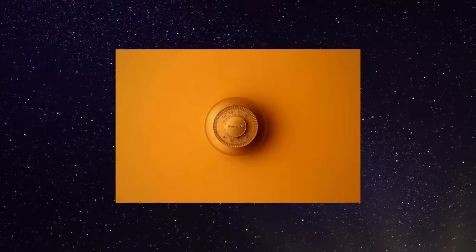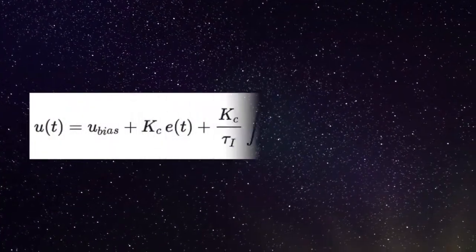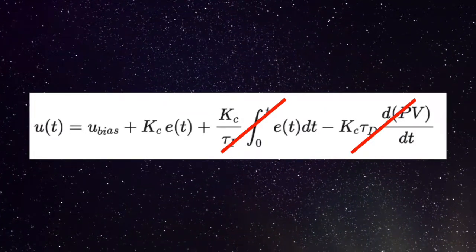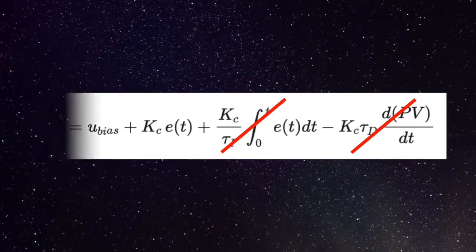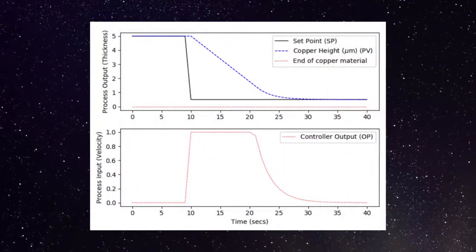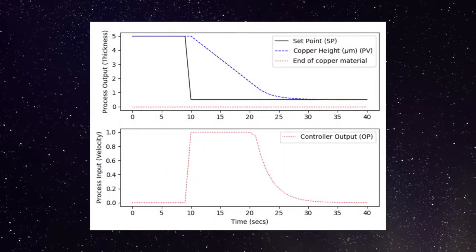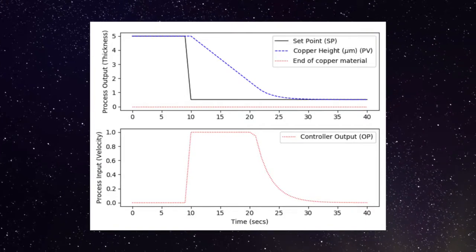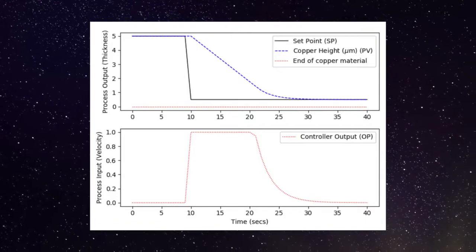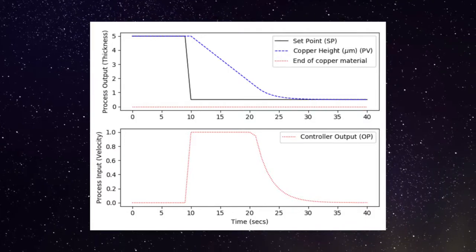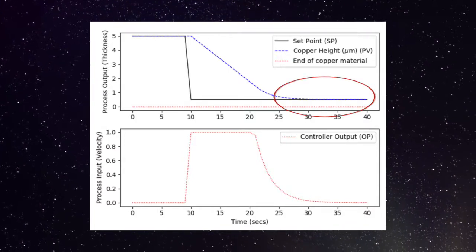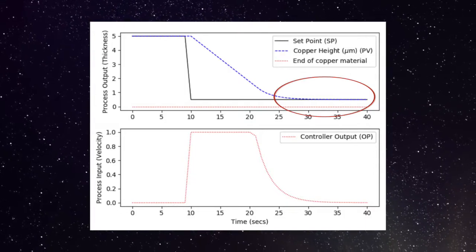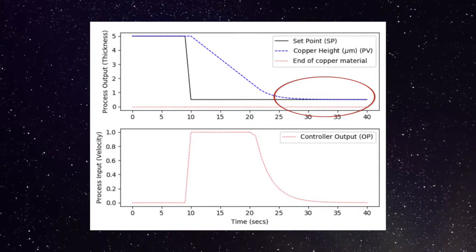For our controller, this meant that a PID should be replaced with a P-only controller. The final Kc tuning parameter used was -1. The final result of the closed-loop control is shown here. The P-only controller performs just the way we want. Specifically, there is no overshoot of the set point. Again, this is important so that we don't lose the wafers that are being produced.